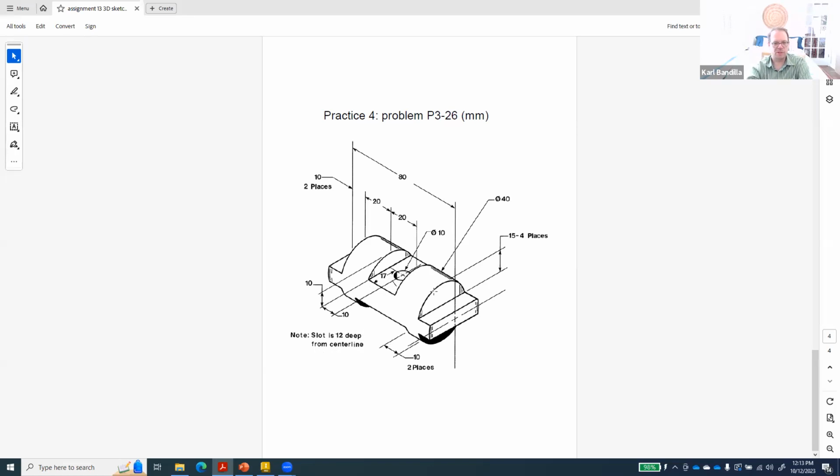So when you go from the center line, right? So it'll be either 12 deep. Well, it kind of confused me there for a second, right? The deep one is measured from the center line, right? So from that center line would be a height, not a depth. So that's why I got kind of confused there for a second, right? But so this distance here is basically whatever the overall diameter is, the radius is 20, so 20 minus 12 is 18, would be this, right? But you can measure it from the bottom up as well.